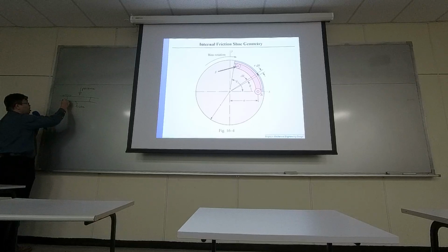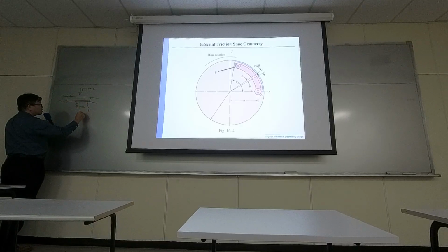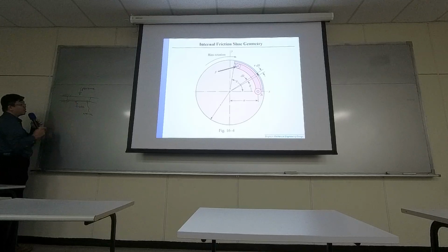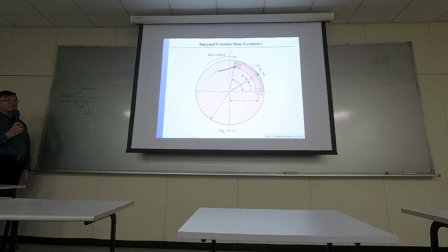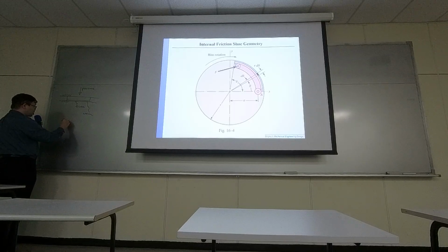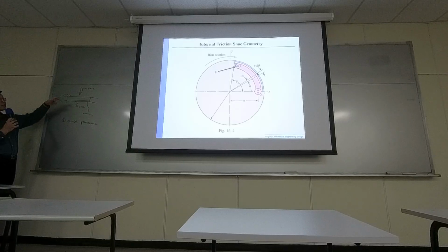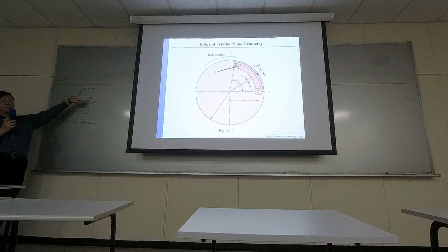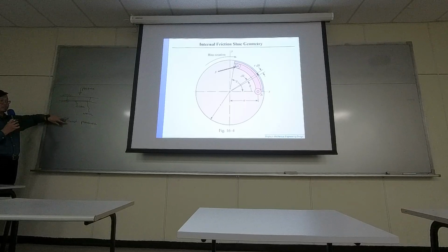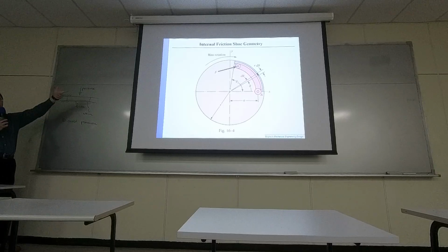and the amount of wear at the interface depends on certain models. So one model is called the constant pressure model. In certain geometry, you can assume the pressure applied to the entire interfacial surface is constant. Does that mean you have constant wear? It depends on the geometry. That's why we need to do some math.